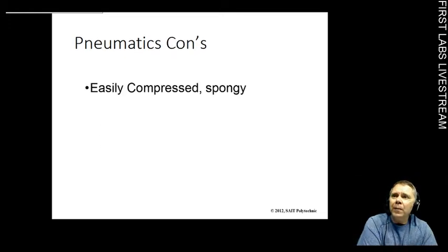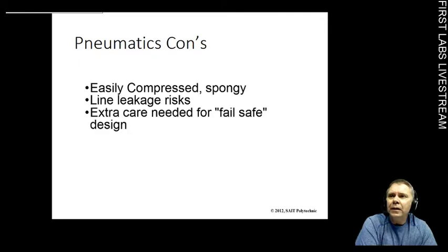Some of the cons of pneumatics, though, is that they're easily compressed. They're quite spongy. It is air. It does compress. Hydraulics doesn't. Hydraulics is a very, very strong, tight kind of a medium, but pneumatics is kind of spongy. There is a risk of line leakage, of course.